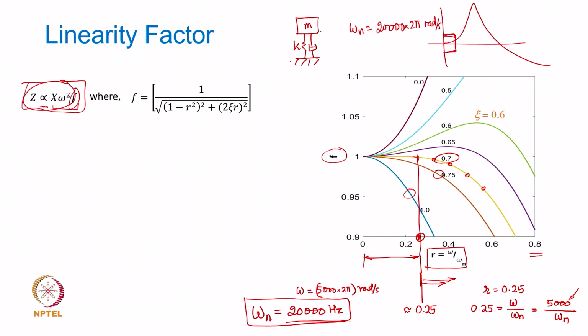That the k should be large enough, right. So, this is what the design is, and then of course, for making sure that the C should be such that the damping ratio is 0.7. Fortunately, these piezoelectric materials do have a good damping property or a damping factor, and so that suffices.